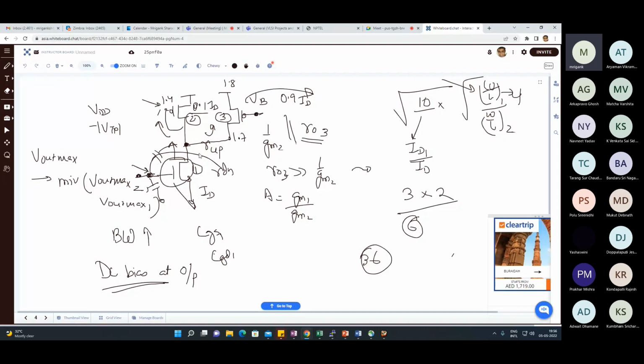So here we can see that this node anyway, we are still having low impedance because R up is 1 upon gm. Therefore, this node is not going to be so critical. Whereas input node, we had a Miller capacitance, etc. So now by the help of this current source, the Miller capacitance will be reduced. Therefore, it will enhance the bandwidth. Without even drawing the small signal model and doing the Bode plot, looking at this circuit, I can make some comments on the bandwidth and the gain and the DC bias, all those things. So this should be clear to you.